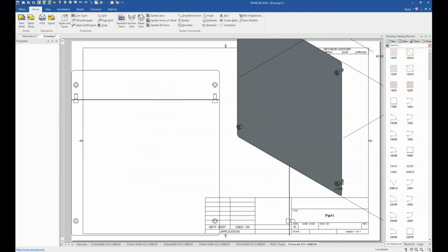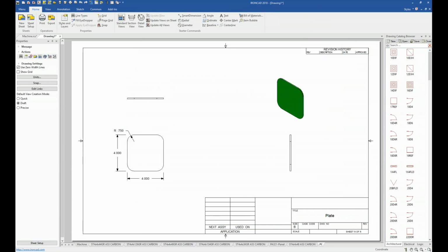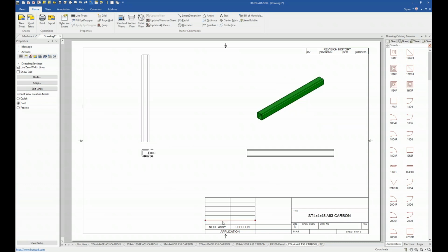It's actually projecting all the geometry for us, resizing it automatically, and giving us all of our sheets. You can see down at the bottom, all of our sheet names were created based off the part numbers in the files. This is our plate geometry, and even the dimensions were transferred automatically, so that's helped us out on the design side, where we don't do any real detailing. Our titles are automatically pulled from the part geometry and populated, so if we select another file here, you can see that title has changed as well.